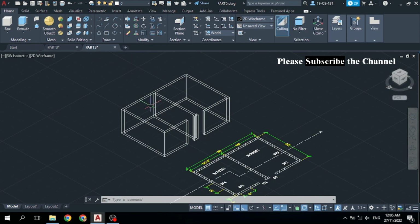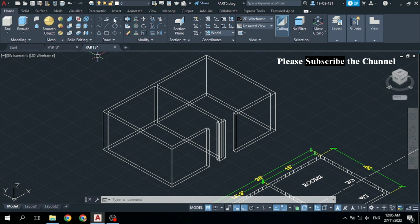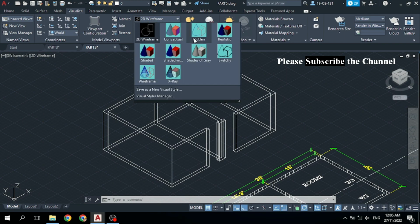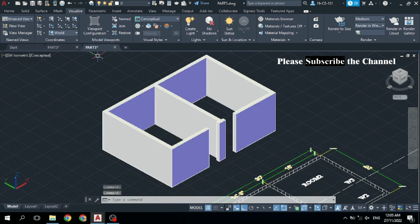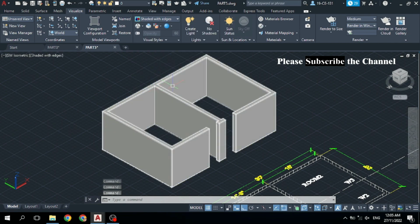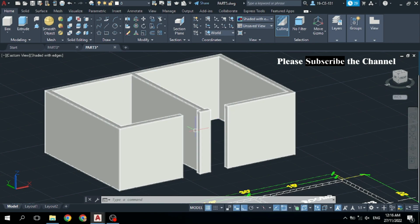And to show it is a solid object, come to visualize. You can see this visualize and click on this 2D, and here different options are available. You can select any of them. Let's click on this conceptual. Now you can see it is shown like a 3D solid, and I would like to select this shaded with edges. You can see we have two opening doors here. This wall has 10 feet height, and our doors have 7 feet height.